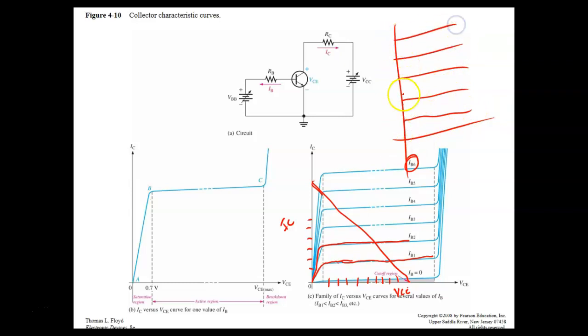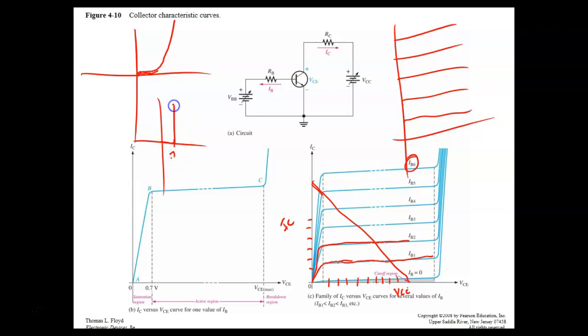But you have to realize it's going to be a slant, just like the characteristic curve for diodes. It actually starts off with a slight slant and goes up like this. But for calculation purposes, we say when this gets to 7/10 of a volt, it goes straight up, because we know it's not going to be precise.